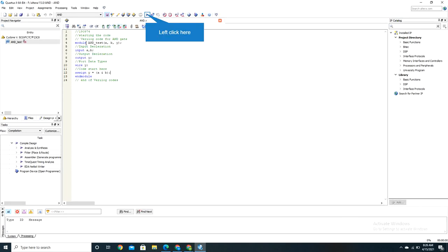With the module, we give the name of the file and the variables used. So first we write module and test, which is the name of my file. Then the ports are A, B, and Y. You can also write C or anything else as you like. Then this is my input declaration: input is A and B in my case, and the output declaration is output is Y.